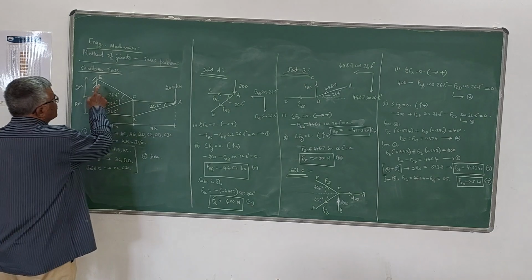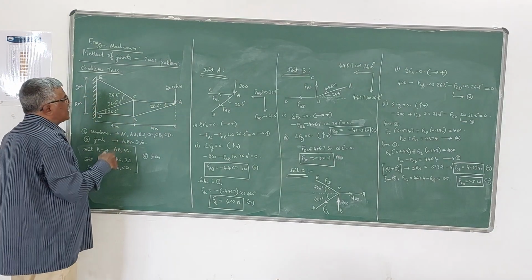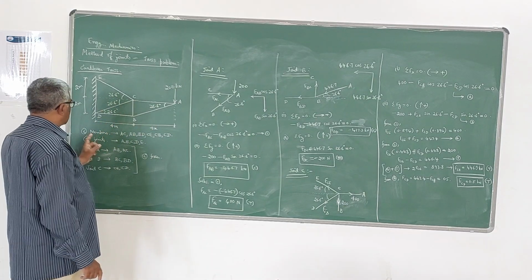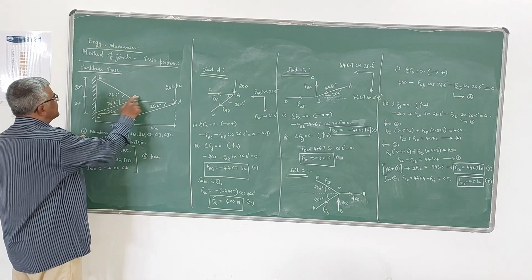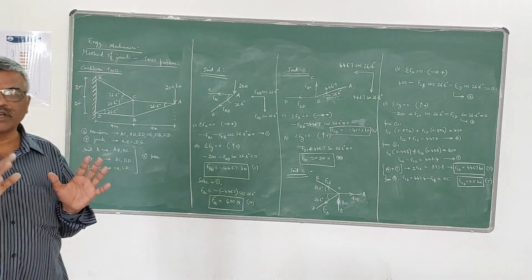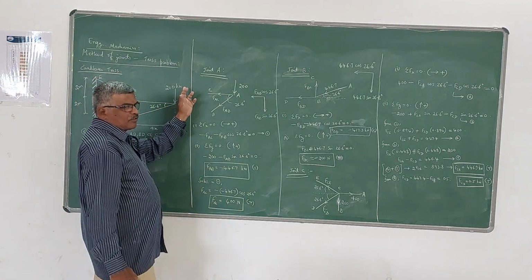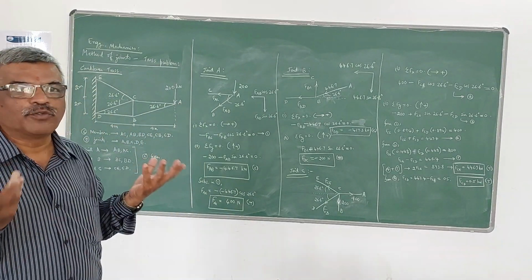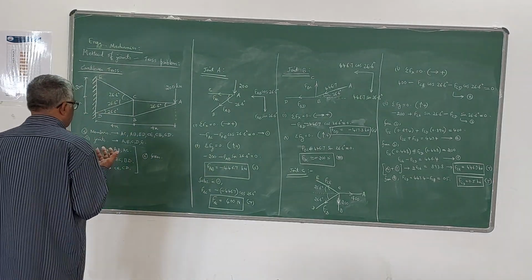So, you can observe here, load is acting at this free joint A. You can see that there are 5 joints here, A, B, C, D, E, and there are 6 members: AB, AC, BC, BD, CD, and CE. So we have to find out the internal forces developed due to this 200 kN external force in all the members. So as already told, the forces may be either tension or compressive in nature in all the members.